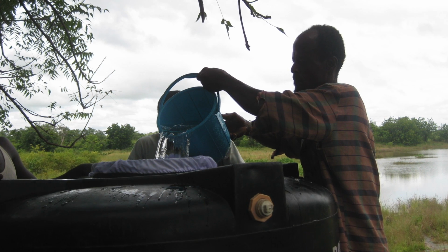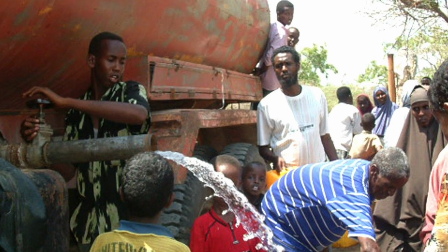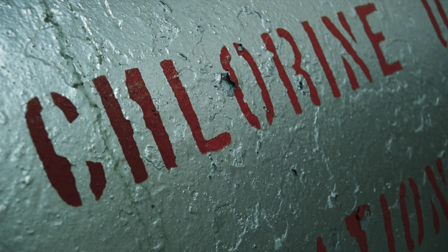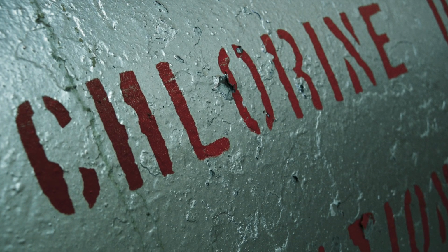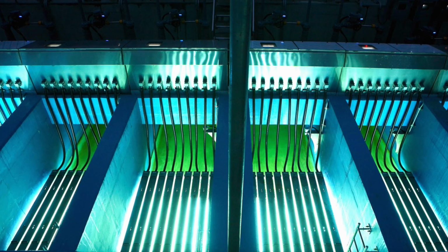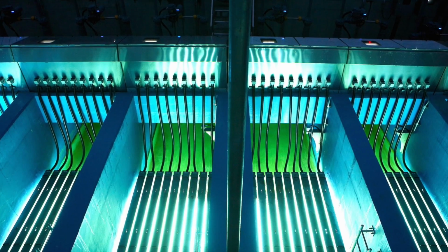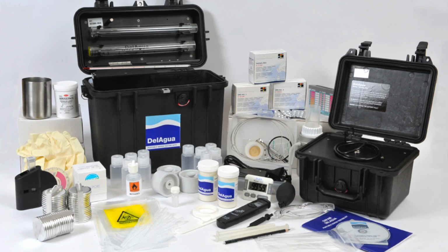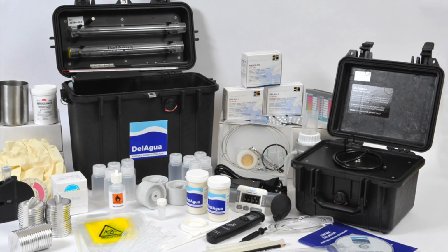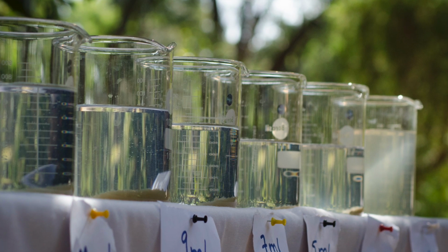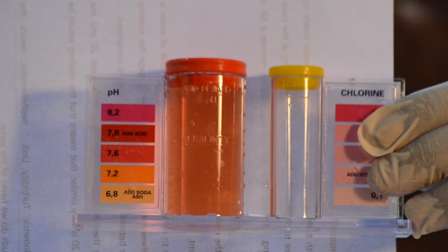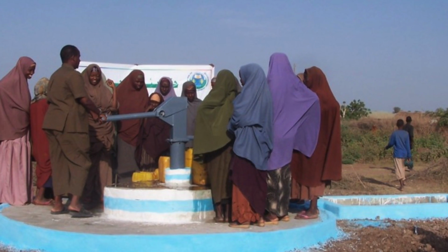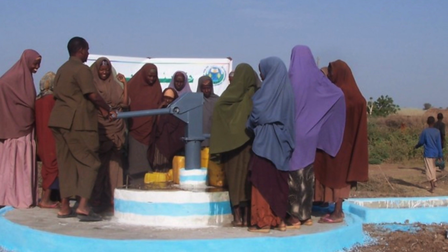Disinfection refers to selective destruction of disease-causing organisms in the water supply. The most widely used process to disinfect water is chlorination. Other processes include ultraviolet or UV light, ozonation, or reverse osmosis. Several tests and pre-treatments have to be conducted to ensure effective chlorination, such as turbidity and pH tests. The following videos will take you through the different steps of the chlorination process.